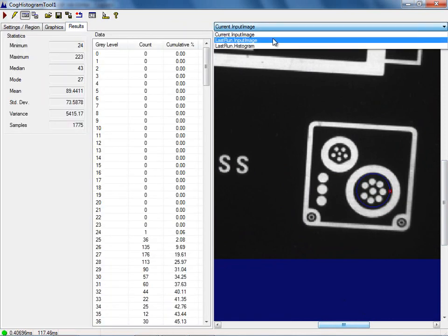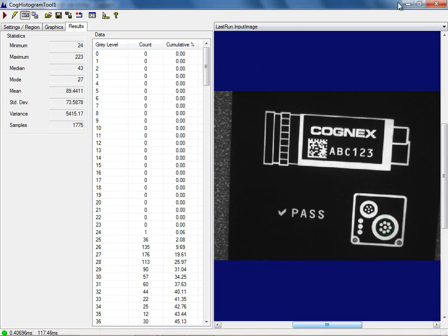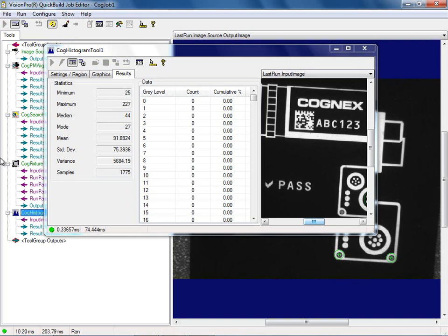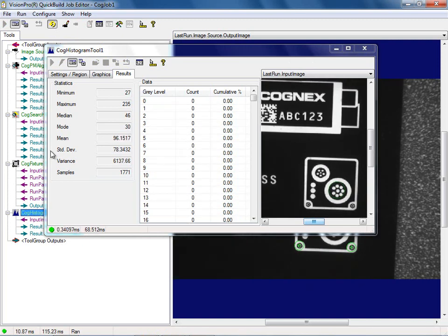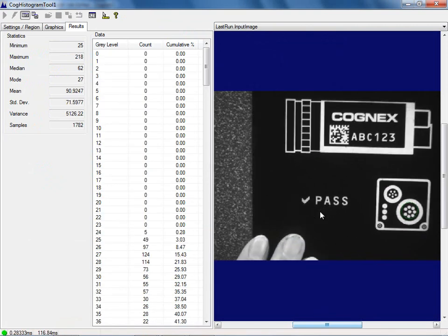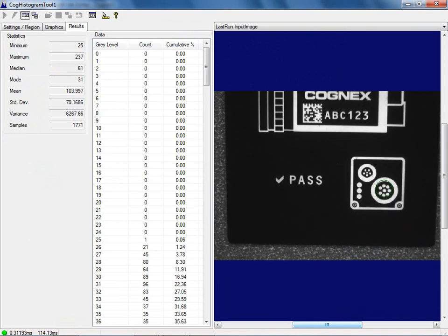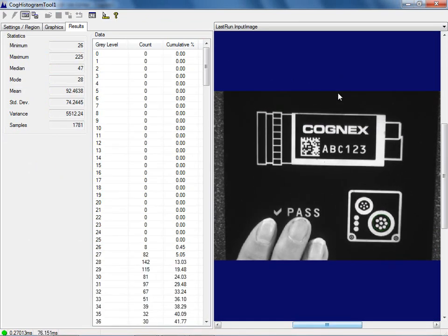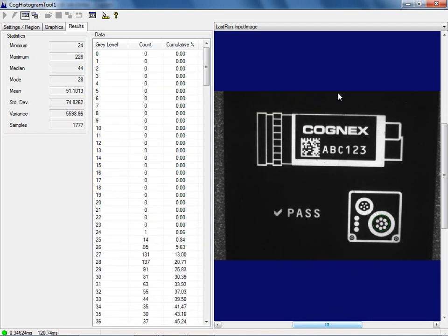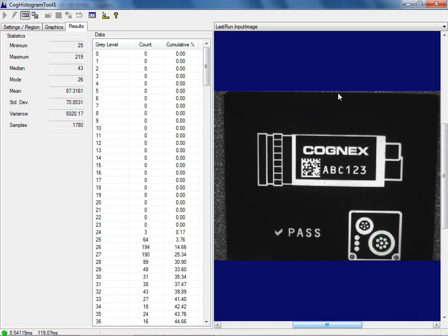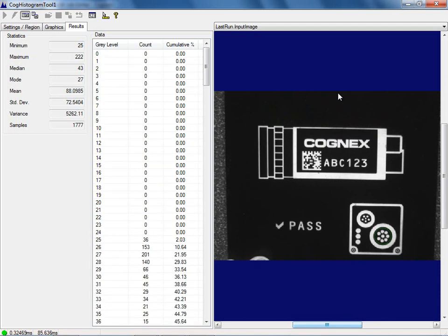We can see with our results that indeed it's there. And if I go ahead and let me reduce this and say run, notice that inside my histogram image right here, it is staying, for the most part, with my part. Okay? Notice it's moving a little bit as I'm moving up here, but that's because my Cognex is almost outside the field of view, so it's getting thrown off a little bit. And also, my camera is actually skewed. I'm coming in at a non-orthogonal angle. So like about right there, that's almost perfect for me.